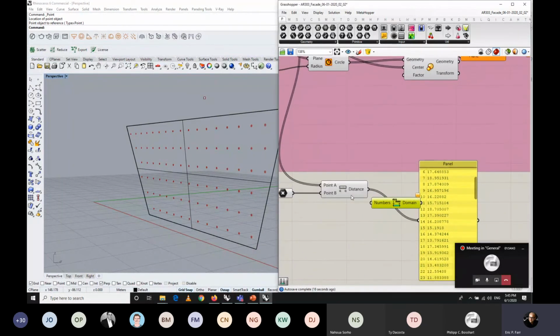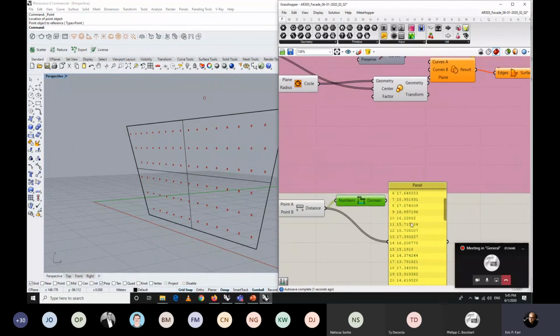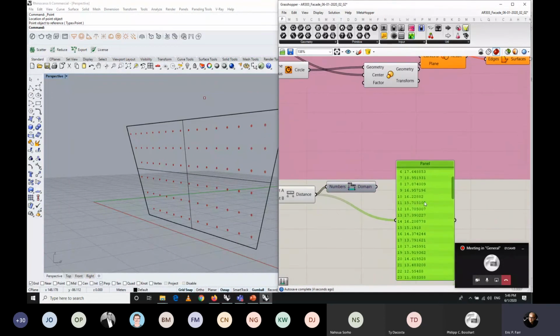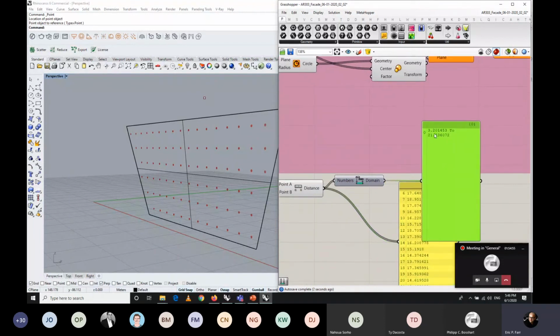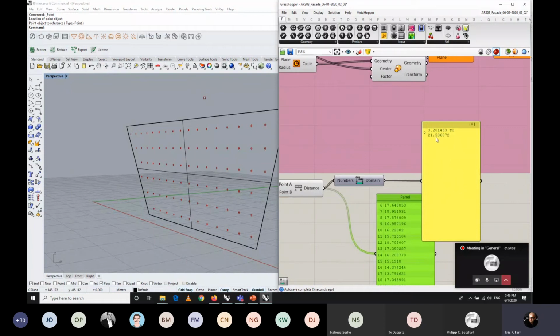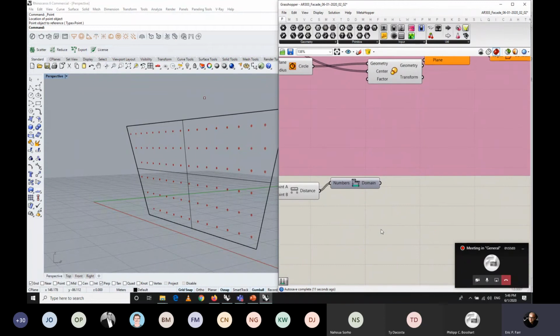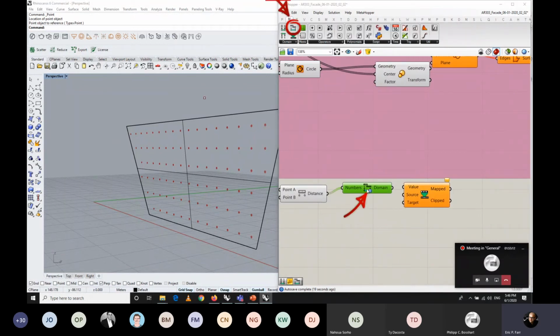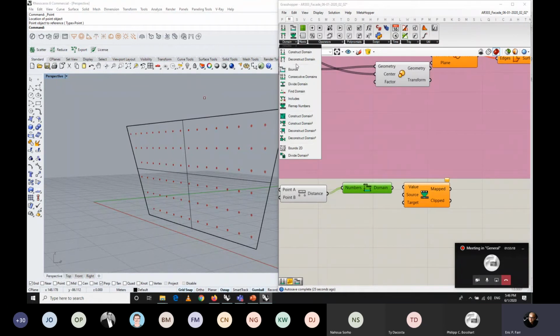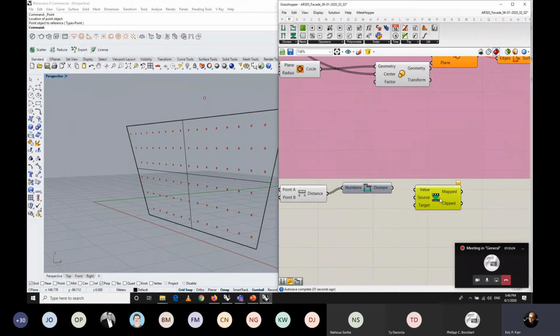So we have a bound in here: the upper bound and lower bound of the data that we got. Whatever we got in here is the domain between 3.2, the lowest number, and 21.5, the biggest number. And what we're having is a Remap Numbers component. You get Bounds under Mathematics, under Domain, and from the same menu you're going to get Remap Numbers.